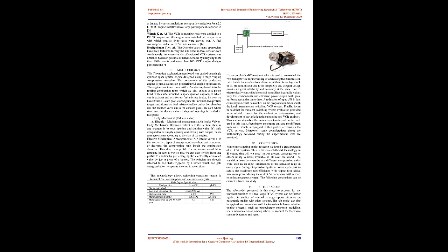Rocopoulos et al. Second law availability analysis performed on a variable compression ratio spark ignition test engine showed that although the compression work increases with the compression ratio, such losses are more than compensated by the expansion work gains and the decrease in energy availability in the exhaust gases. 1. Cutler et al. As a consequence, the ratio between net and gross IMEP increases due to the need of lower intake pressure to maintain the same load.